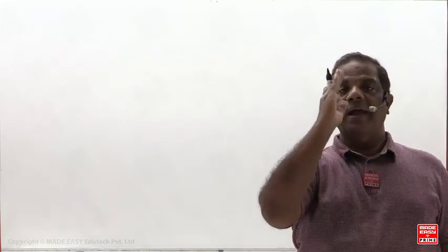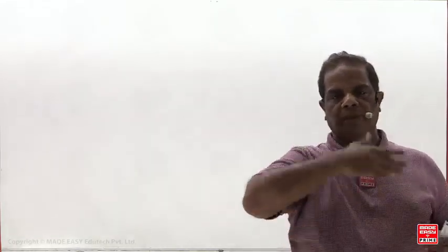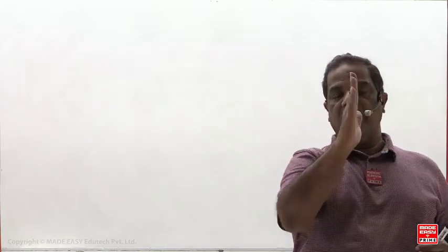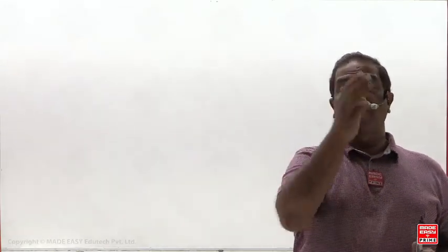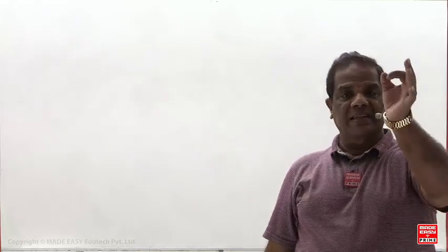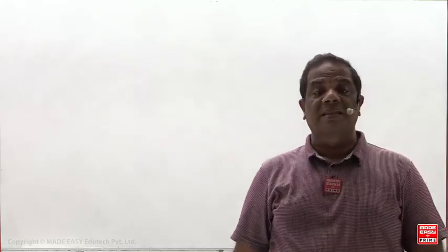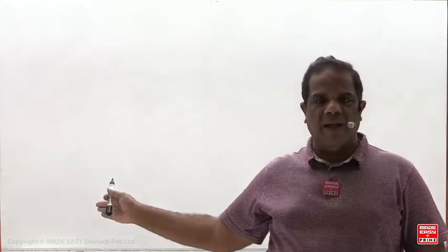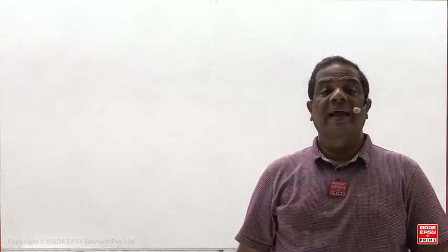Yesterday I studied a rectangular element with X face, Y face and Z face. We have taken this as the Z face, this is the Y face, and this is the X face here. So at a point, how many mutually perpendicular planes are there? At a point, there are three mutually perpendicular planes. So a uniaxial state of stress means stress is developed on only one perpendicular plane, and the remaining two perpendicular planes have zero stress. Yesterday, when we were studying pure axial loading, we took the cross section as the X face, with the polar axis taken as the x-axis.